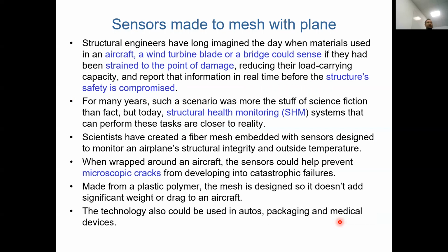Now there are sensors, piezoelectric based sensors. We use strain gauges, which are built into the aeroplanes. We use them for structural health monitoring, or SHM, we call it. Now, if there is an abnormal crack or abnormal strain, these sensors can measure it and feed back into the system.